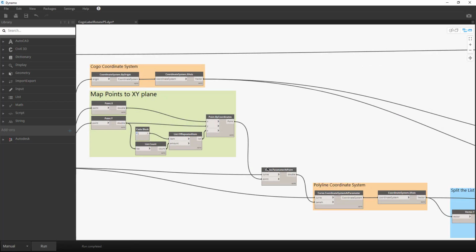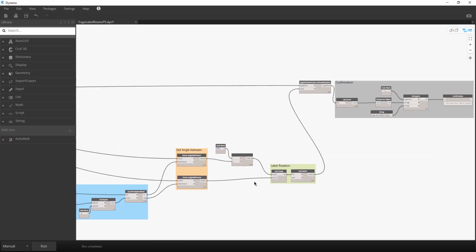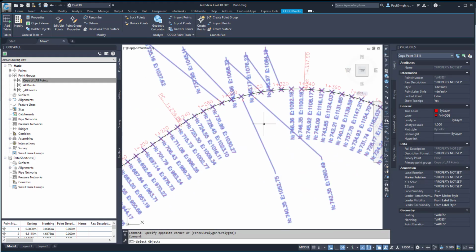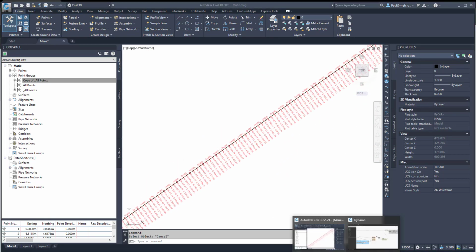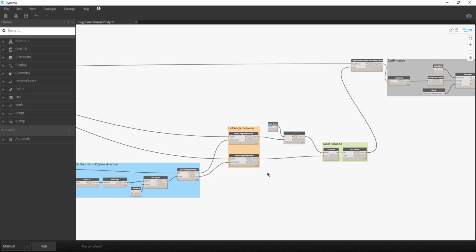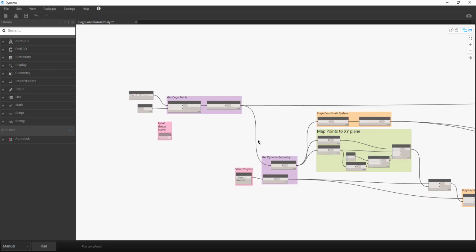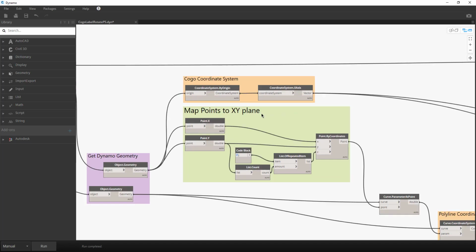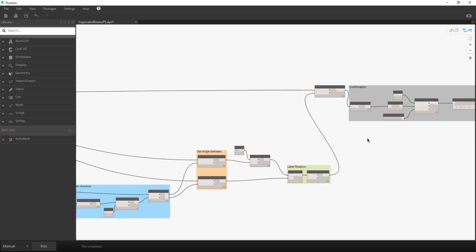This time we can see, even though that COGO point has an elevation, the error is eliminated. And the script concludes successfully. So this is an example of where Dynamo is starting to get used with Civil 3D. The graphs are not always going to give you what you'd like, especially if you download them off the internet, but maybe with a bit of changing of those graphs, you can then get hold of the correct result.